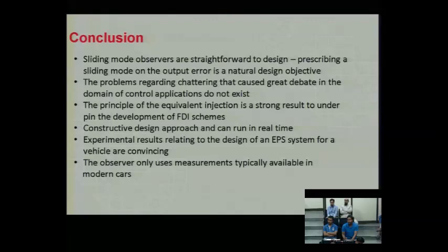I didn't fully understand the question. I think what you're saying is if you use an estimation method to construct a signal, how can you use it in the control system? Well, you can use it by feed-forward injection. That's what feed-forward control is. Feed-forward control says we know the signal.